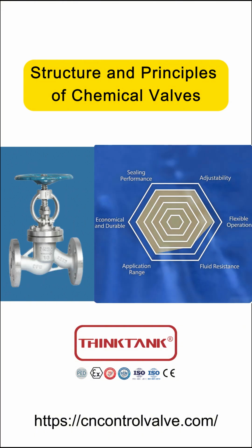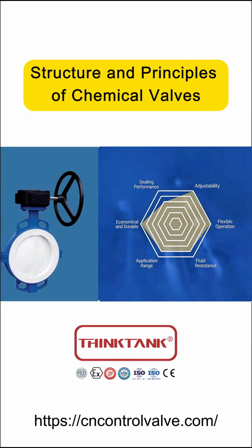3. Globe valves have high fluid resistance, only recommended for small diameters where there are no requirements on medium pressure loss. 4. Butterfly valves are actually quite comprehensive valves. With the development of technology, their sealing, durability, and applicability have been greatly improved. They are flexible and adjustable. They are commonly used in low pressure.